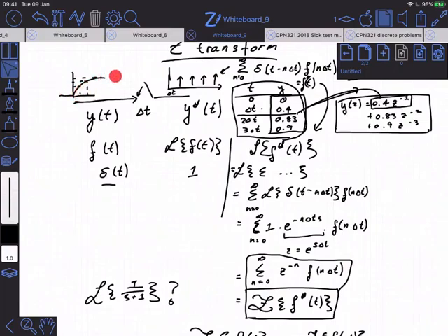We started off with a continuous signal over here, which we sampled. We introduced this mathematically convenient object, a pulse train object, where we encoded the values of the sampled signal at the sampling intervals as the magnitude of these Dirac delta impulses. Now, I've taken care here to draw these without a height, because theoretically these Dirac deltas, if you were to be able to plot them, remember they would be infinitely high, right?